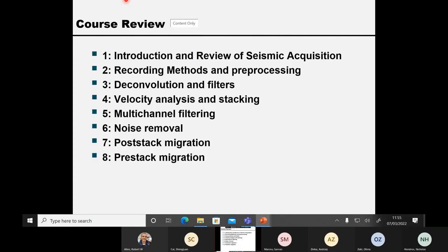It's easy, right? If the dipole is not minimum phase, we can simply swap the two elements. That only changes the phase, but does not change the total energy, because the total energy is a squared plus b squared, so it is always the same.